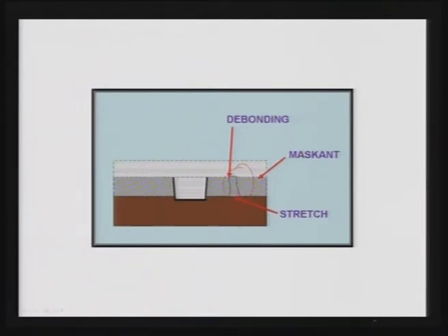So, one should be very careful and check carefully that there is no cracking, no debonding of the maskant from the workpiece, so that the material does not get removed from the undesirable area.